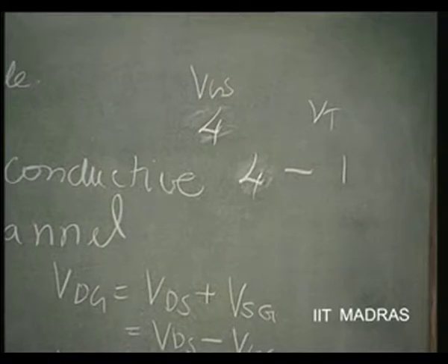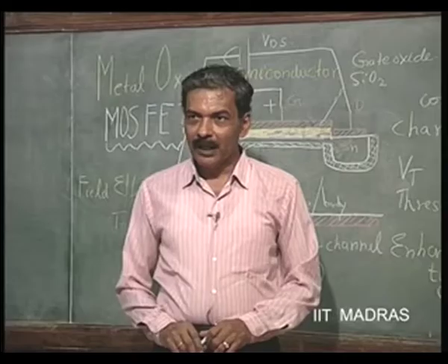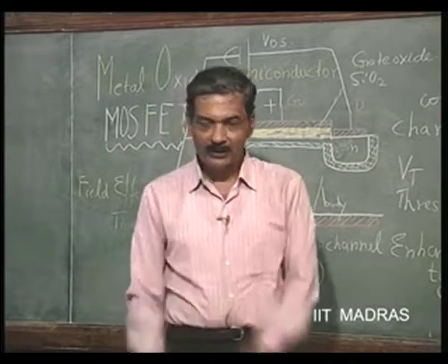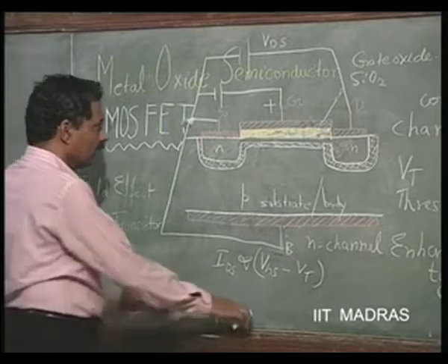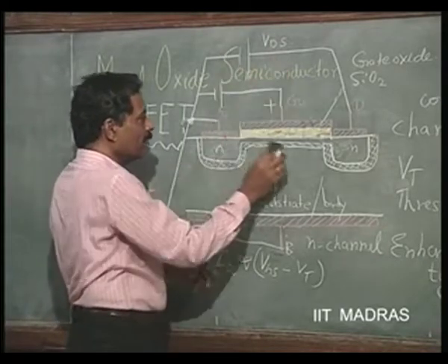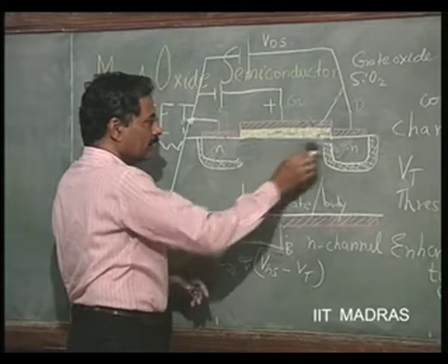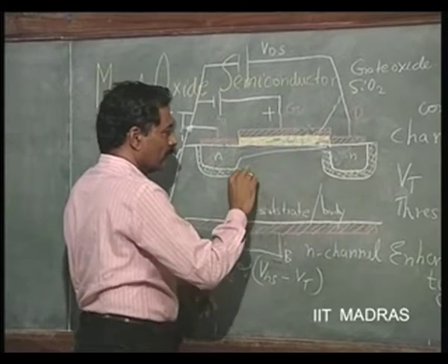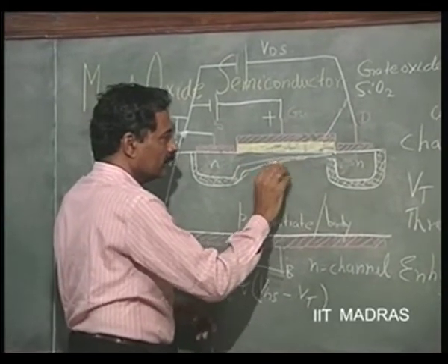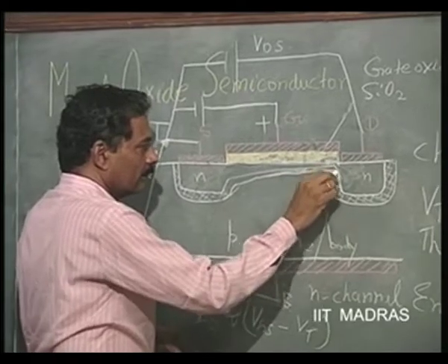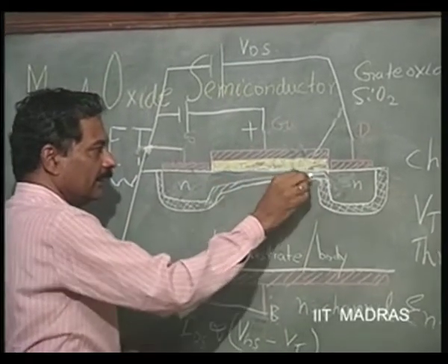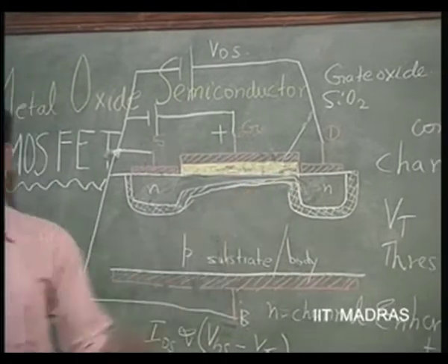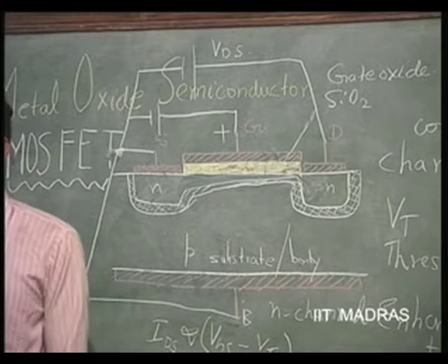So, that is what is called pinch off point, after which the channel at that point is going to remain closed. So, let us picturize this. What is going to happen when I apply a voltage like this is that the depletion layer width is going to extend here and close the channel. This point where the channel is completely closed is called pinch off point.